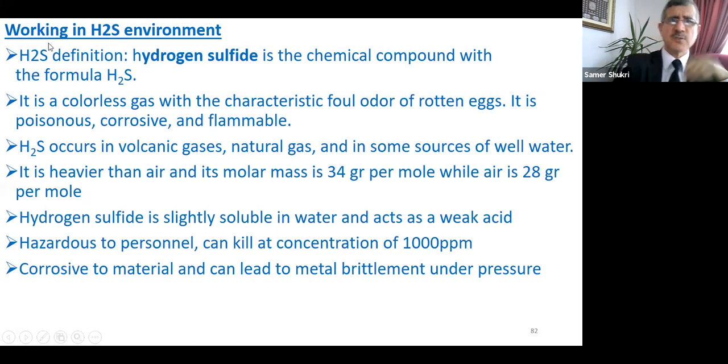While working in an H2S environment, all of this equipment, either wireline or coiled tubing, should be suitable for H2S environment. Otherwise, it will be embrittled due to the corrosive action of the hydrogen sulfide.